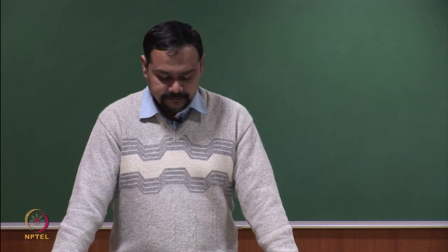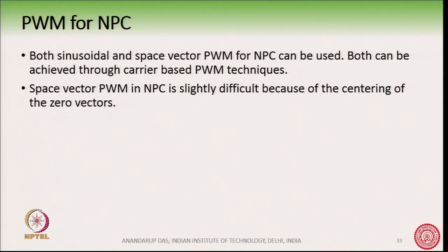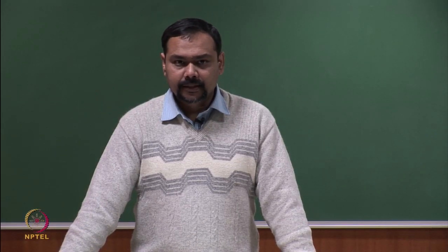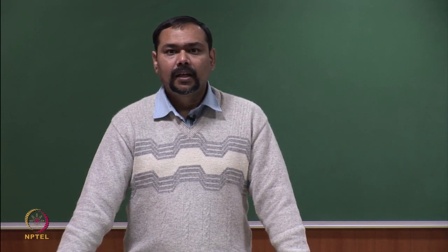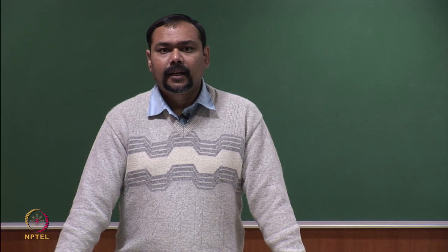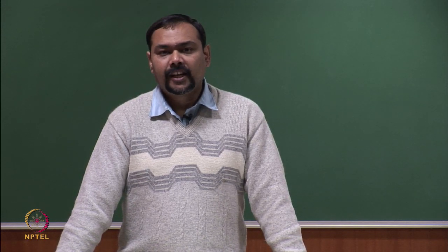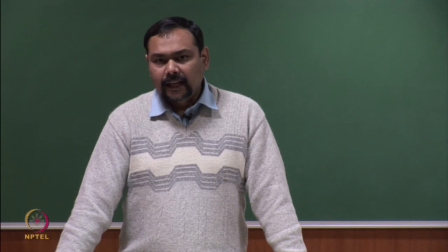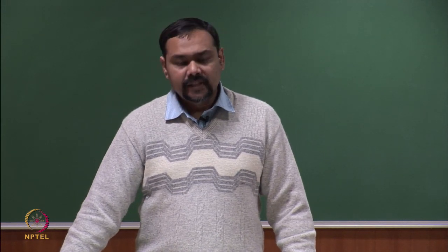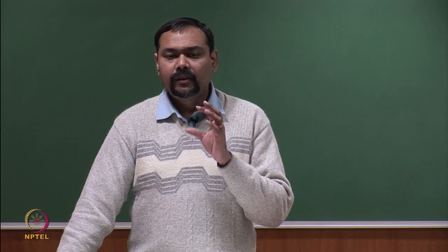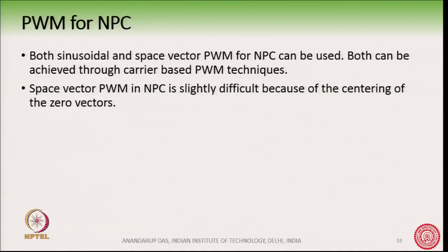3 level NPC. Now, for switching NPC, we can use both sinusoidal as well as space vector PWM, and both of them can be achieved through carrier based PWM techniques. Okay. And in this case, the space vector PWM in NPC is slightly difficult because of the centering of the 0 vectors, and for this we will see a strategy which we will elaborate in this session.